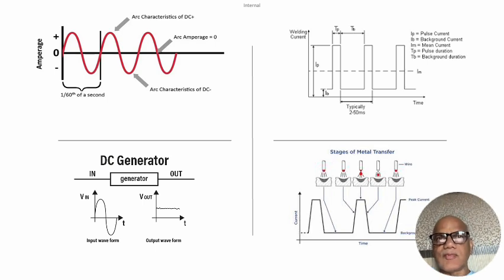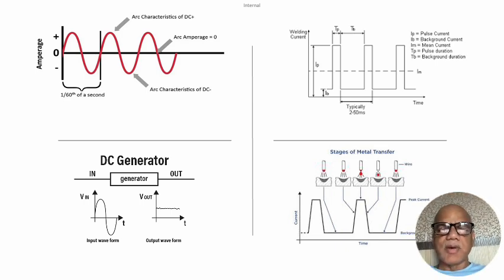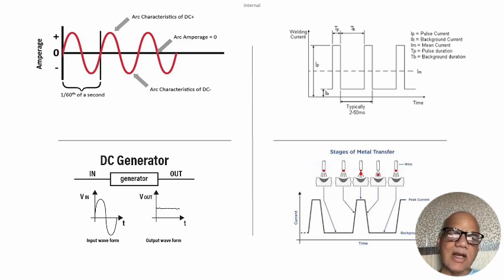That gives the best welding without spatter, with complete fusion, and the kind of homogeneity it creates because of the vibrations, or because the lamellarity of the weld is destroyed, and you create a very small turbulence. That turbulence helps in maintaining and retaining the chemistry and avoids segregations if there are alloys which have a higher segregation tendency, plus the fusion becomes very good.